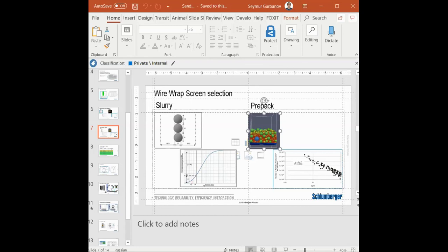So there is another issue, because when you're producing, the solids come from the formation. The literature says sand production is producing the load-bearing sands, which means you're removing the particles which take part of the load. So you have cavities around your casing and eventually you will have tectonic movement or collapse of your open hole, just because you have void space and your formation is not able to withstand those lateral forces. So you may have damaged your lower completion.